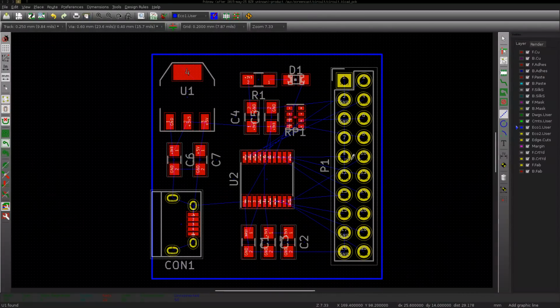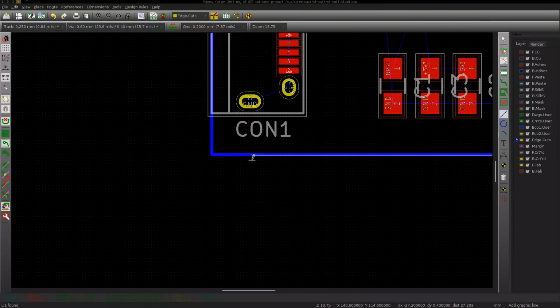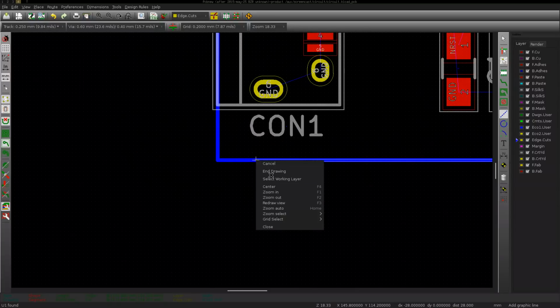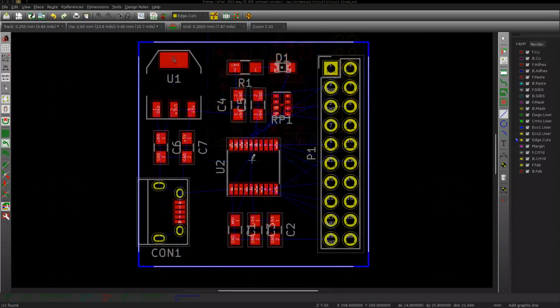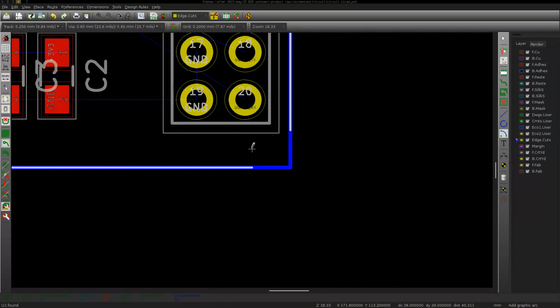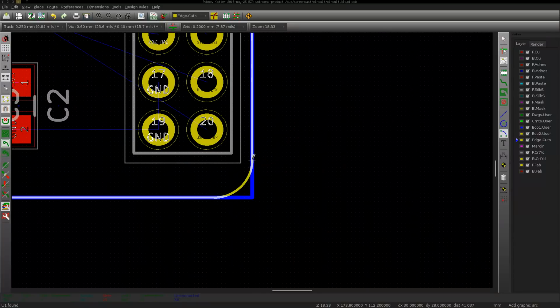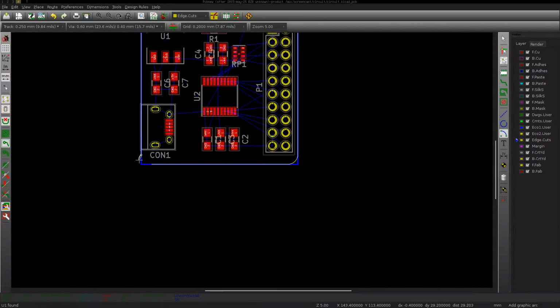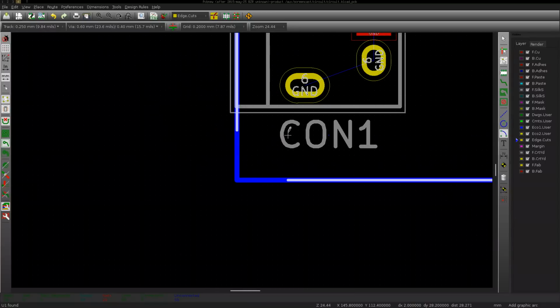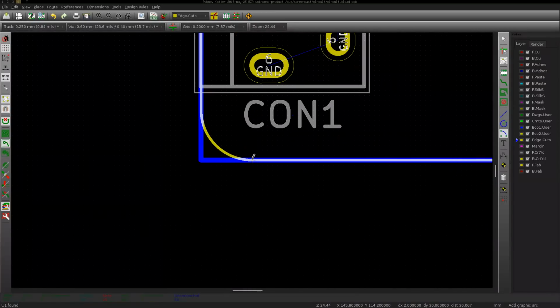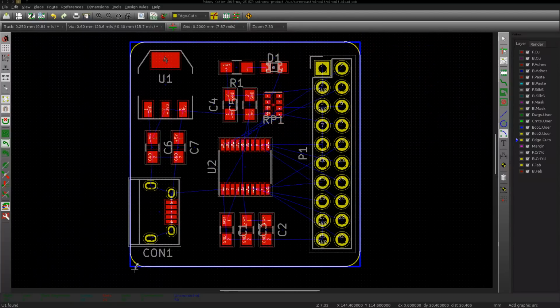Nice. Okay, now let's switch over and use the edge cuts layer, which is there. And go draw some more lines. I'm going to pull them out from the corner a little bit because I'm going to do rounded corners. And for that, I'll use the arc tool. There we go. Click arc. Start from the center and drag out. Nice. Go over here. Click in the center. Drag out. Click again. Nice. Okay, there we go. Done. Delete these construction lines because I do not need them anymore.